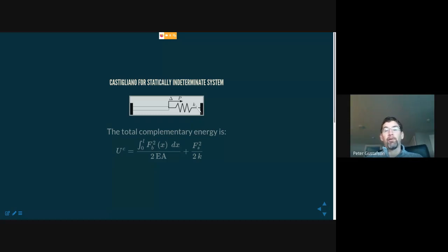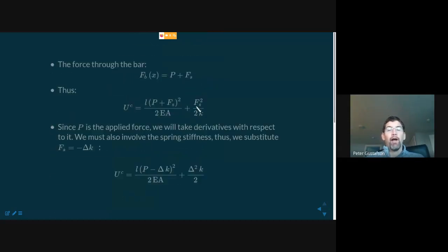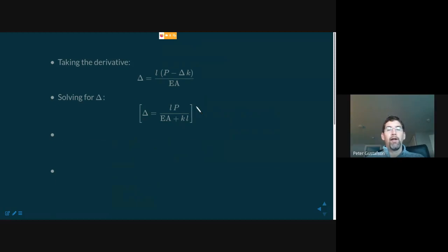Now this just becomes an axial bar. The answer I've predicted is delta equal to PL over EA plus 0. So PL over EA is absolutely the change of length for a constant cross-section, constant material, linear elastic axial bar. So that is a nice little sanity check.